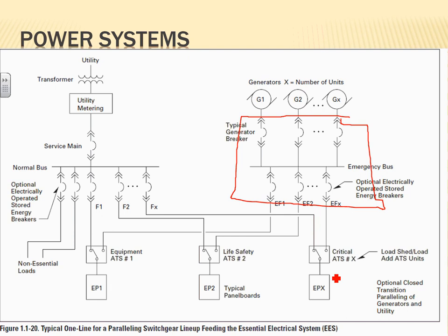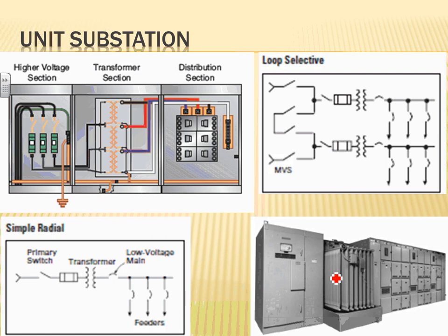Typically this is for hospitals, where you have another source, not just a feeder, another source of power next to you. Okay, so I thought I'd just go over these, because that's where the source transformers make all these configurations. I would dare to say 95% of you guys use a radial low voltage. You might go radial medium voltage. If you have hospitals, you have another source of power, which is a generator. The high end of generator is probably switchgear.